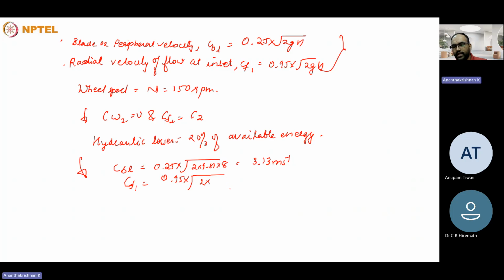So in the hydraulic efficiency, the total head at the inlet and the hydraulic losses have to be taken into account, as well as the efficiency parameters. So what I'll try to do is calculate this first and then determine the whirl component at the inlet from the hydraulic efficiency that is given in the graph.